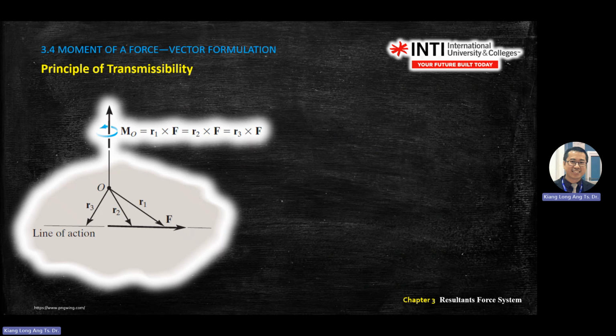Yeah, I mean, this is 2D, so you see it as 3D. Okay, so again, this is vector. It's not the normal 2D diagram. So for 2D, yes, you can say it equals F cross D, the distance, but this one is R. R is the vector direction to that force.